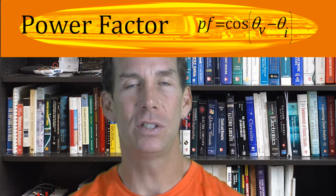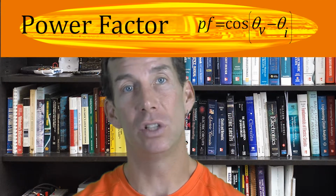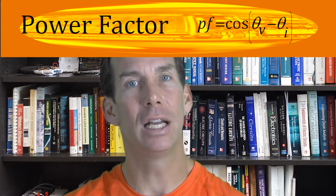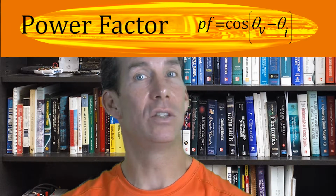Since in many power systems the voltage is known, apparent power can indicate how much current carrying capability is necessary for the system. Apparent power does not have any indication of the relative phase of the voltage and current. To deal with that, we have a quantity called the power factor. The power factor is the cosine of the difference in phase between the voltage and current waveforms, and therefore can have any values between and including -1 and +1. Values of plus or -1 indicate that the power is entirely real, while a value of 0 indicates that the power is entirely reactive. It should be noted that for anything that uses power, the power factor will always be positive.